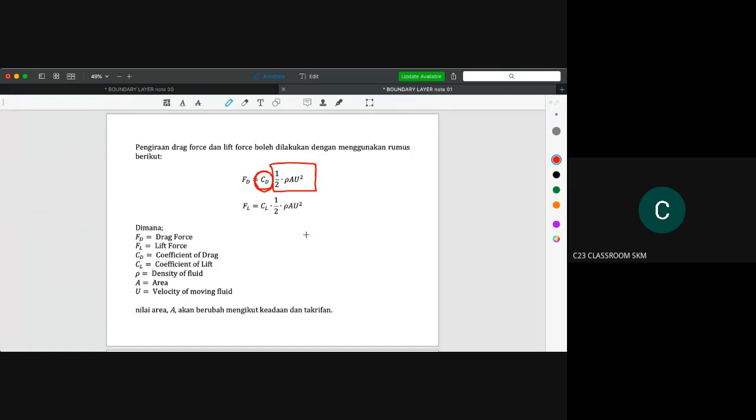So I think in fluid mechanics 1, you could imagine that, for example, we have a tank like this. When the water flows out here, we have a coefficient here, CD, which is actually the coefficient of discharge. Because in a real situation, the velocity that comes out from this hole is actually a little bit slower compared to the theoretical calculation. Same goes to this idea. So we need to put the coefficient here to make sure that our calculation is the same as the experimental works. So please remember this equation, because we will use this equation in the calculation later.